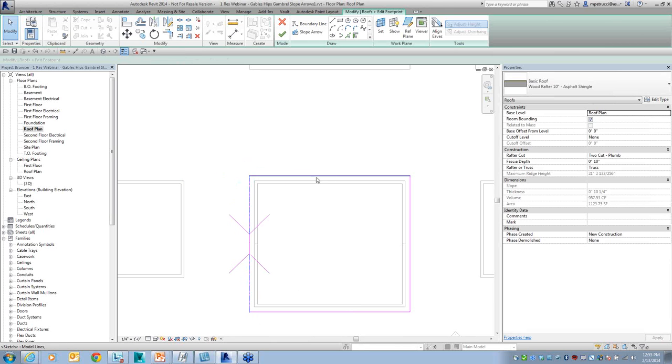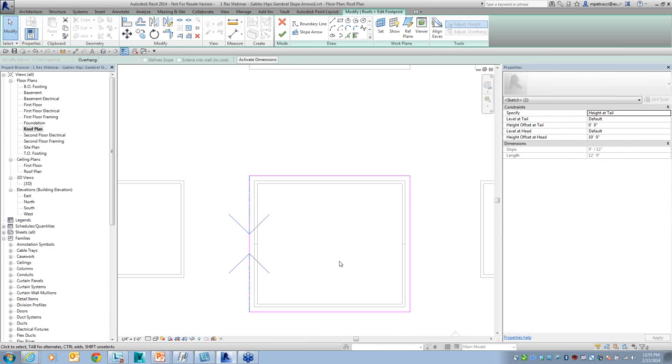So now what I'm telling Revit is, on this edge give this a slope, and give this a slope. Well, what is that slope? If I select the slope arrow, I can come over here and decide how I want it to slope the roof. I'm going to select the slope option and use a 9/12 slope. That's what I had before. If I finish this off, it's going to look exactly like my last roof.